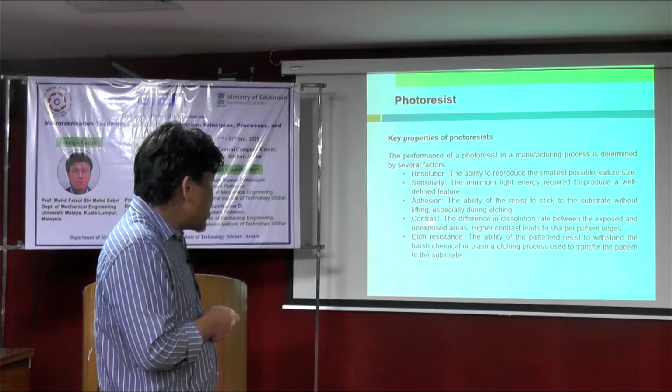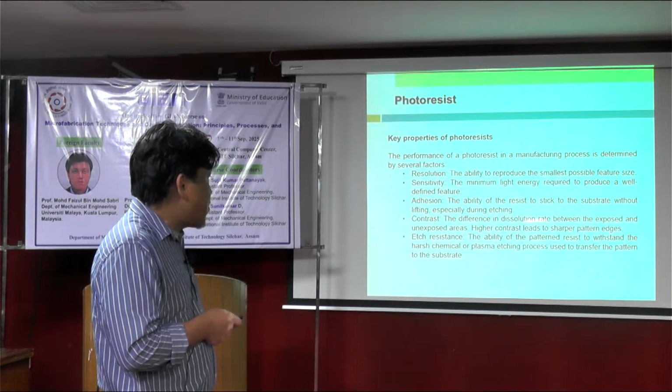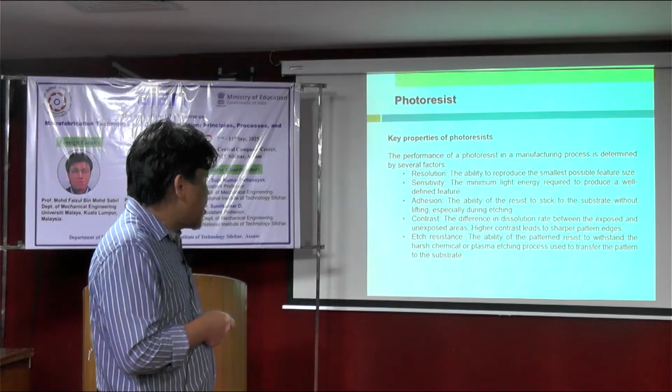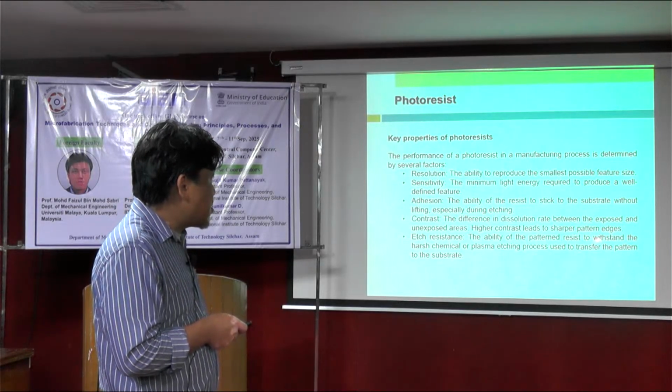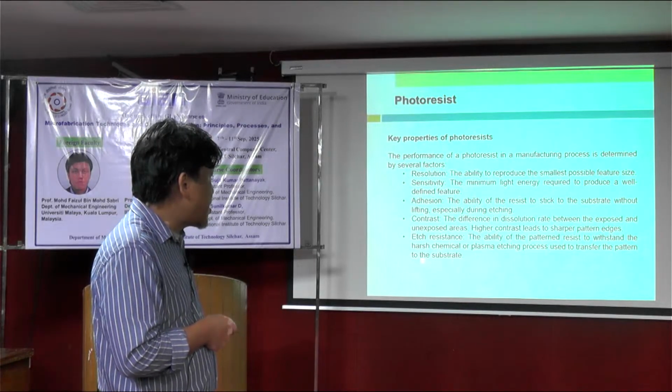And contrast, the difference in dissolution rate between the exposed and unexposed areas. Higher contrast leads to sharper pattern edge. And etch resistance, the ability for the pattern to withstand the harsh chemical or plasma etching process used to transfer the pattern to the substrate.